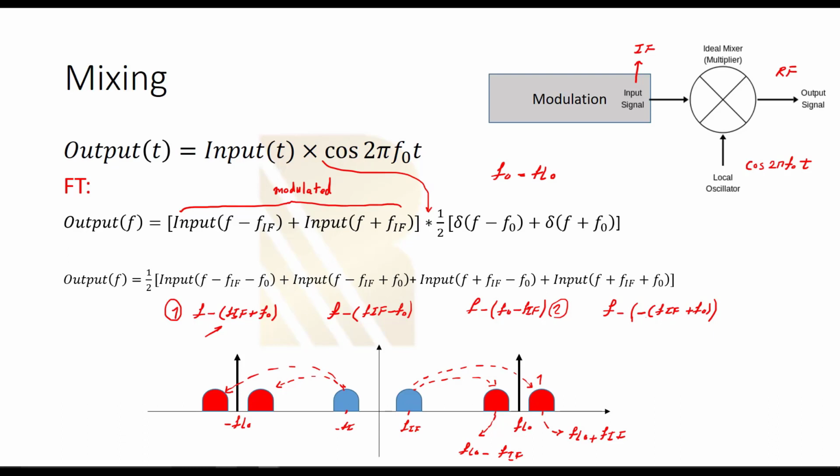So they are going to the higher frequencies, and as you see, they're really close to FLO. It means that these are higher frequency, and we are successful. We upconverted the channel as we expected before. But generally, we have to know that in books or some pictures, we always show the positive frequency. So we now actually reach the figure that we had previously.